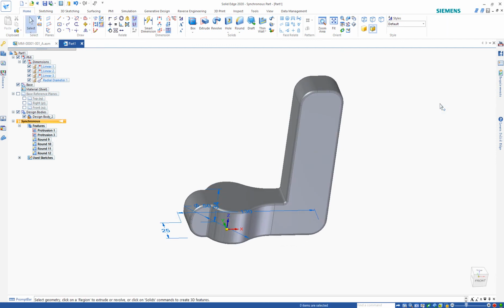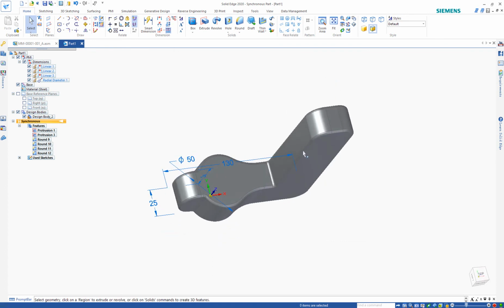So what if you forgot to put in the dimensions into Sketch like I did before? I only drew the line but didn't put any dimension into it. You can actually put 3D dimensions onto the model directly. For example, I want to change the distance between this point and the back.